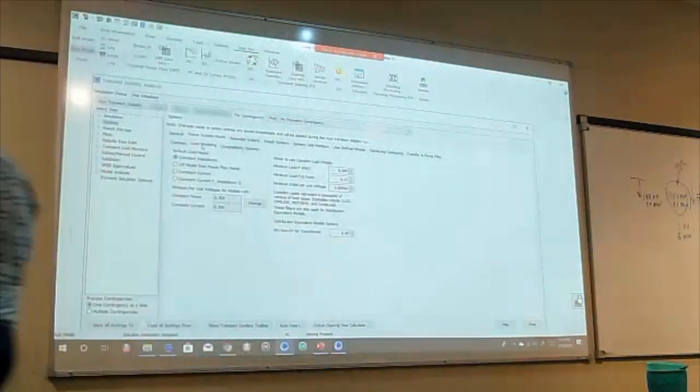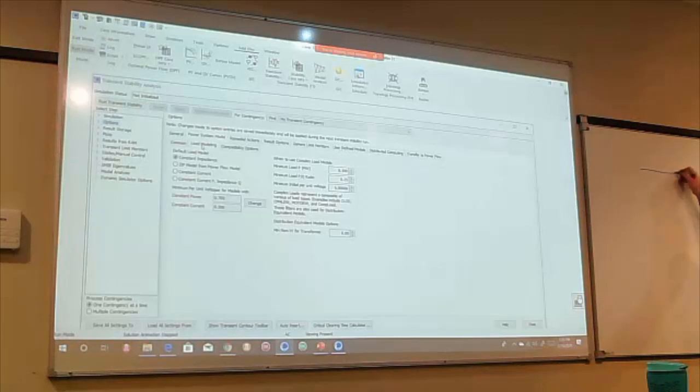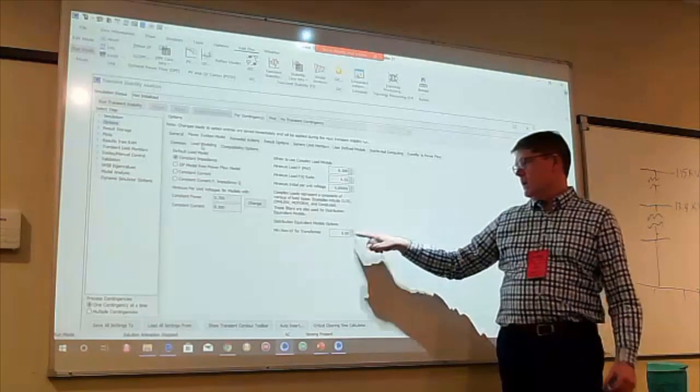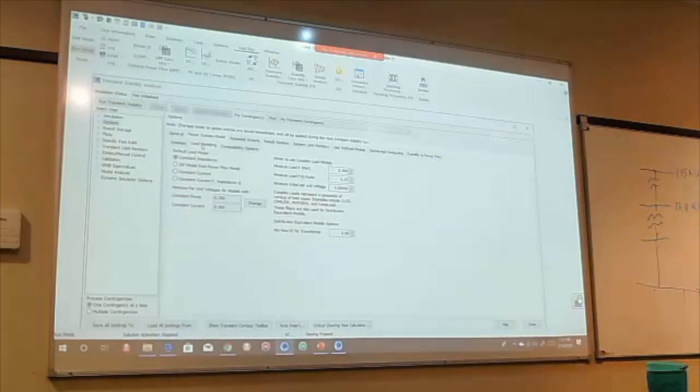So what was happening is people would have, in the power flow case, a 115 kV bus here. In the power flow, they might have a step down to 13.8 kV, and then they would have their load. And they had put that in the power flow. And then they assign this load to a distribution equivalent that also has a step-down transformer. So when we put it in the composite load model, we do this and put our loads down here, but this is silly. Those aren't there. The point is, in the power flow, somebody already put the step-down transformer. So this says that any load that has a nominal kV below, usually I set this to 40, then just ignore that transformer in the input data.